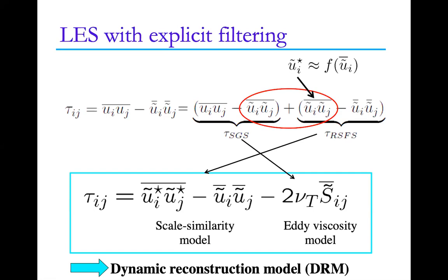So the key idea here, and to try to summarize why this approach is different than just a standard eddy viscosity approach, is that we have the turbulent stress divided into a resolved subfilter scale portion that you can actually reconstruct, plus a subgrid scale.